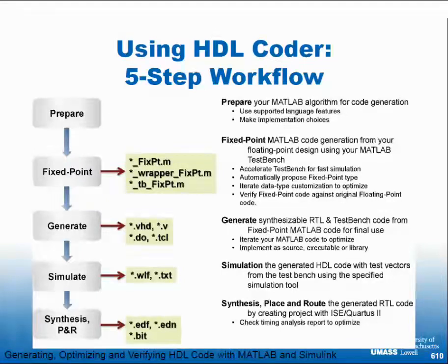So what you can do here is you can test your fixed point model of the design that you're building against the floating point model that you originally had. So your test bench has the accuracy of floating point, and your design model, I'll call it your HDL model, is the fixed point that's synthesizable. But the verification allows you to converge those two. So any loss of accuracy that you incurred, you can find out if you still meet your specs.